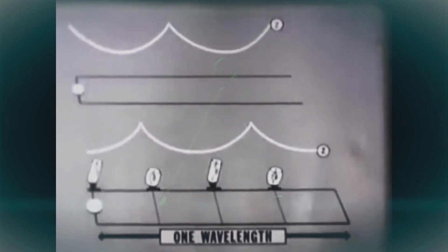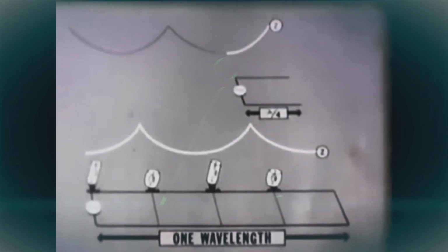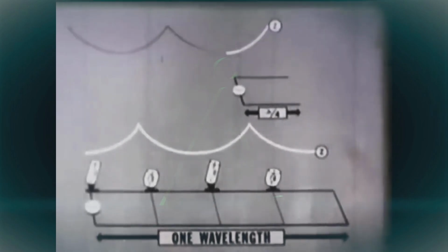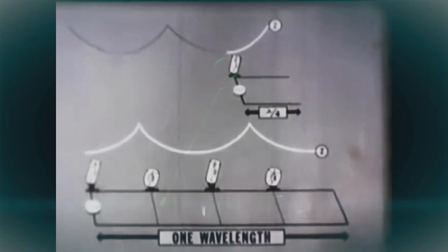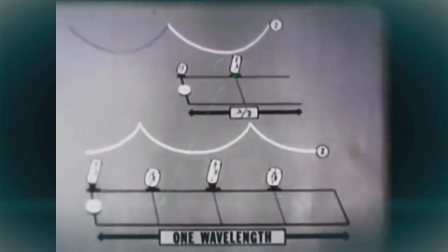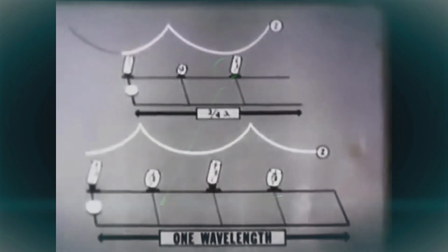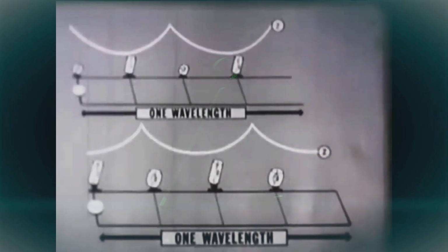The behavior of our open line can be investigated in the same manner. At the 1/4 wavelength point, the generator sees a condition of minimum impedance. This circuit can then be considered a series resonant circuit. Each time a 1/4 wavelength is added to the circuit, the condition changes. Thus, open and closed end lines can be used as parallel or series resonant circuits, according to the length of line used.